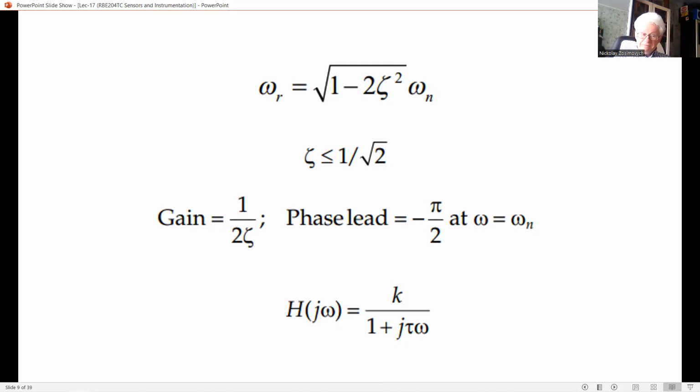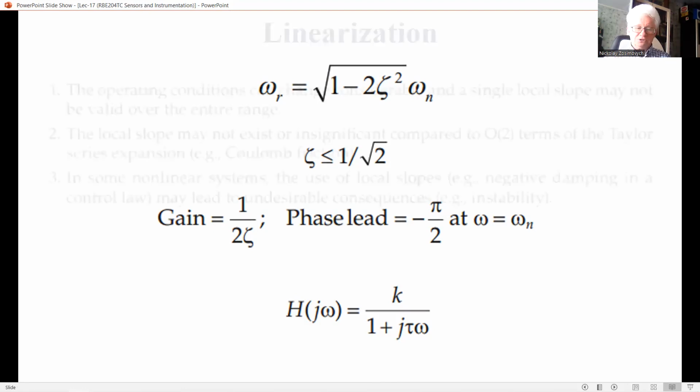Since the gain k can be normalized to 1 and adjusted physically by an amplifier or computationally by simply multiplying the response by a constant. And further, it cannot represent an undamped system, and hence a condition of resonance. In particular, a simple oscillator model cannot be obtained by cascading two first-order models.